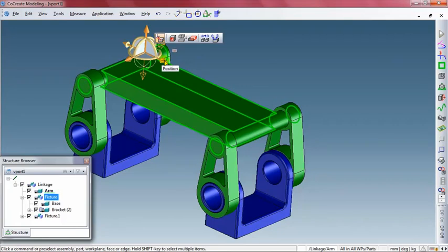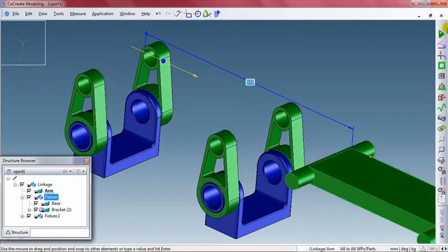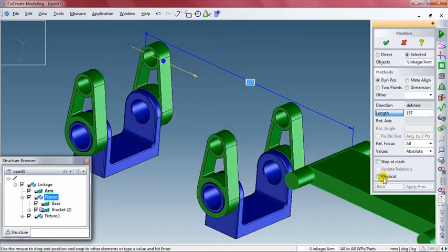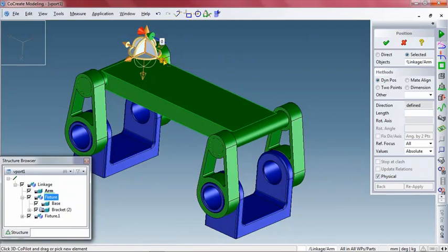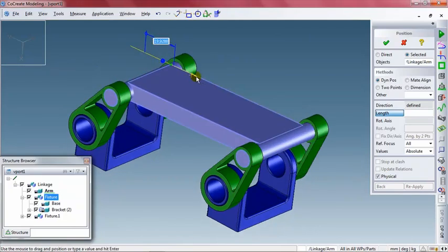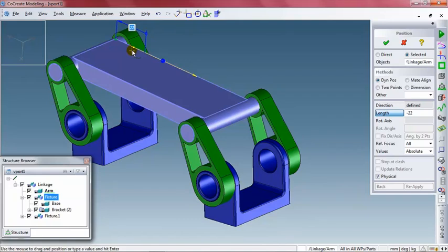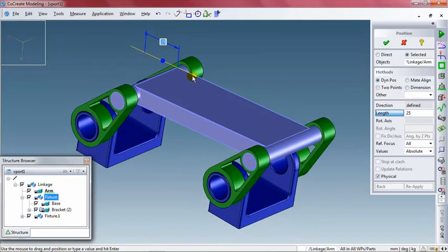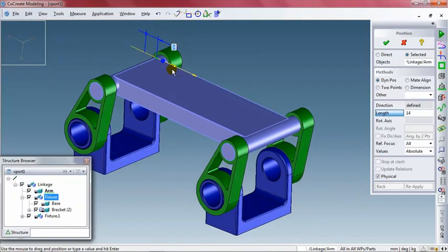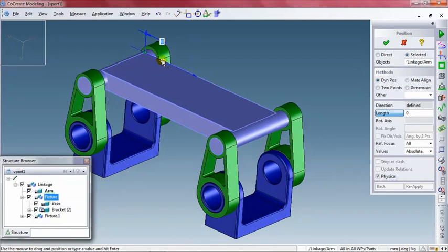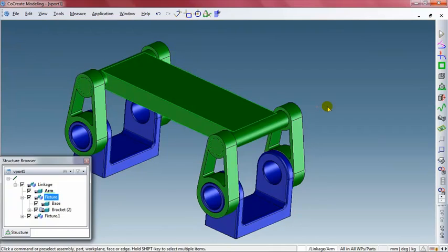This time, I will use the physical simulation option. This function will calculate live how the parts would move in conjunction with each other as one unit with no relationships defined. However, the blue base parts rotate out of place, as they do not have a relationship telling them to stay stationary. We can create a quick relation set to fix these base parts in place.